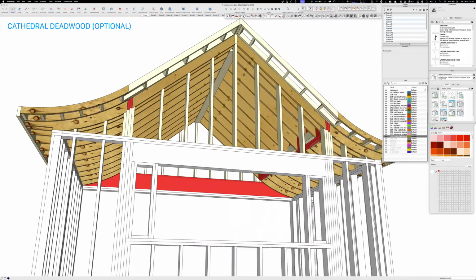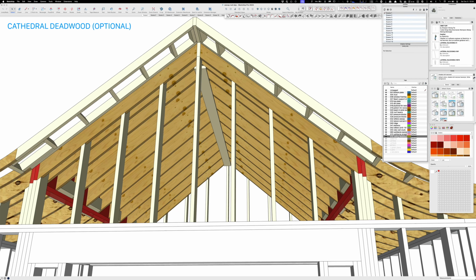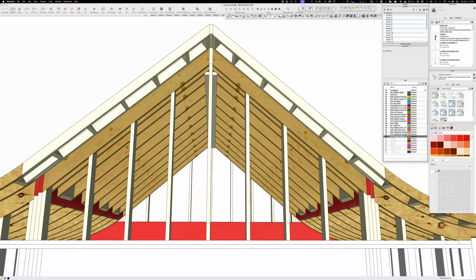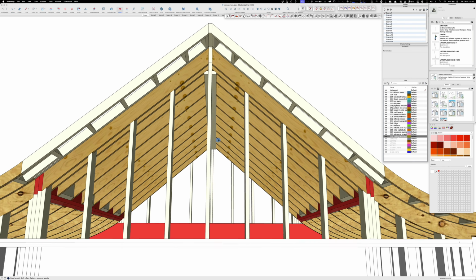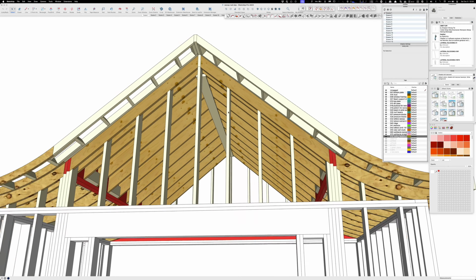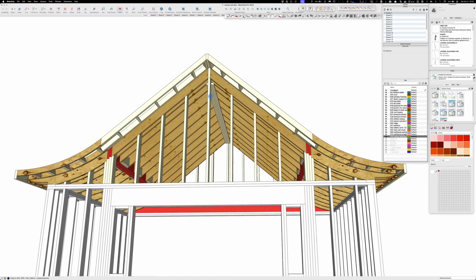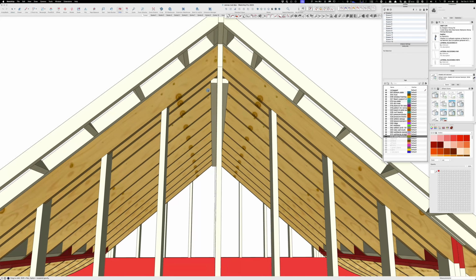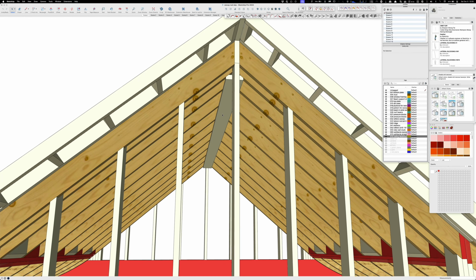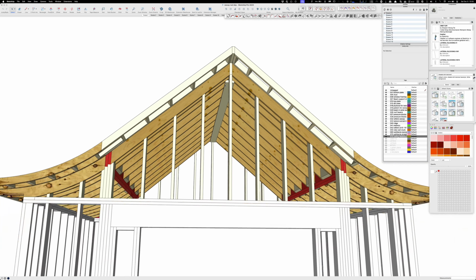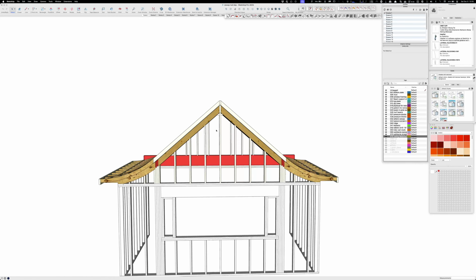I've seen this done a lot. Some people like the peak to go right to the top, but then it's kind of a pain for the electrician to do anything. So if you had any kind of suspended lighting or fans, what I've been told is, hey, bevel a 2x6, center it, and shoot it in there so that you create a mechanical flat spot that they can work from. And who knows, somebody might want a fake beam even. You could build a box down and over and back up, make it look like a big piece of timber if you felt like it.